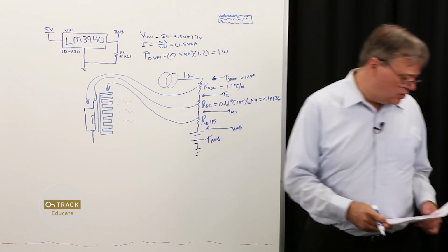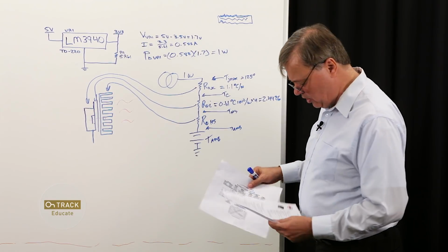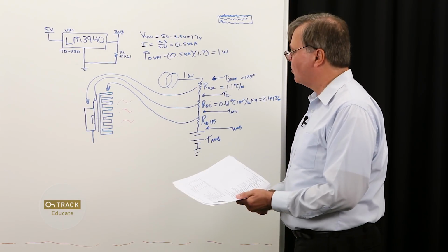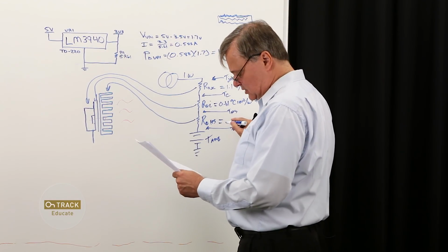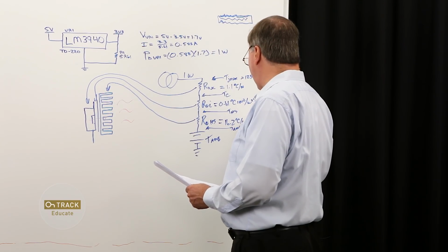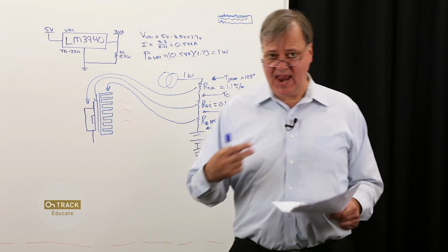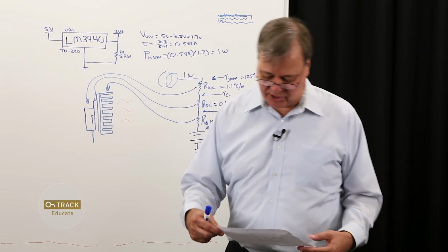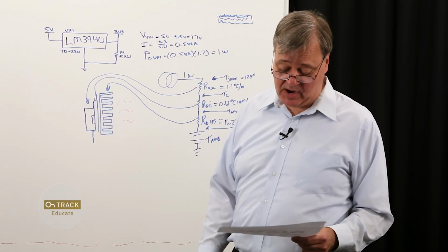Okay, now we come to our heat sink. Now, a couple of considerations here. First of all, the published value for thermal resistance for this particular heat sink that I'll show you here momentarily is 16.2 degrees C per watt. Now, this is a nominal value that considers natural convection, no forced airflow or anything of that nature. And it's also kind of an averaged value, okay?